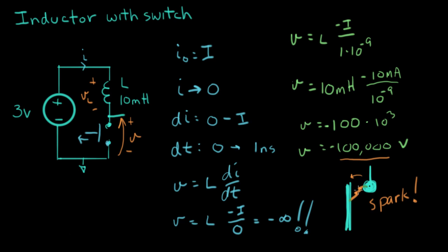When you open a switch, there can be a little spark that goes between, and that gives this equation, this dI/dt, enough time to release that energy, and that current from the inductor continues to flow and go over into the switch. That current will flow, and it does it by breaking down air molecules.